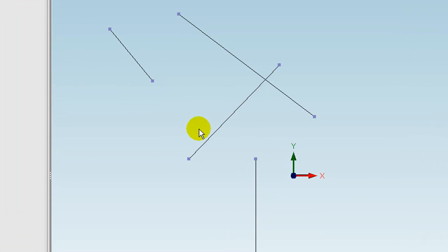If this is the case, we need to wake this point up first by touching it, so that's now woken up. And now, as you can see, it will look for the intersection point with that line and this line. If it was looking for it everywhere and there were many lines, it could be a massive intersection search, even with elements off the screen. So you have to wake the point up. So let me just draw a new line so that clears the woken up lines. So see, it's not working.